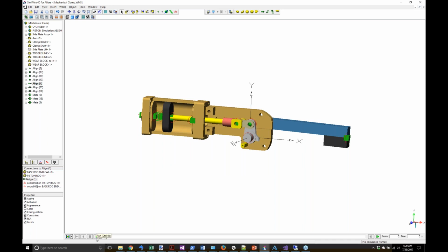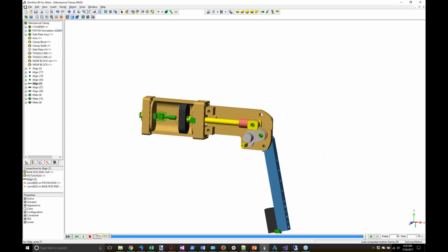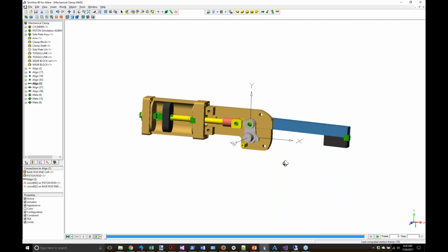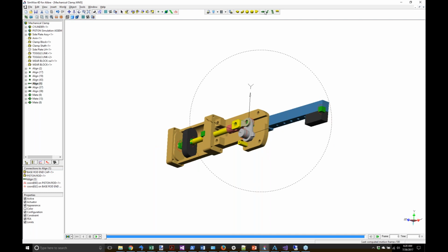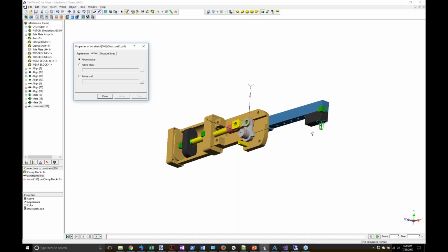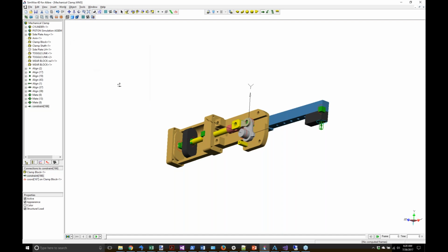All right, so now the motion simulation is set up. Let's go and run this, and we see now it's not falling under gravity. It's actually got some control to it. Let's go and add a force. Let us add this force to act 500 newtons in that direction.